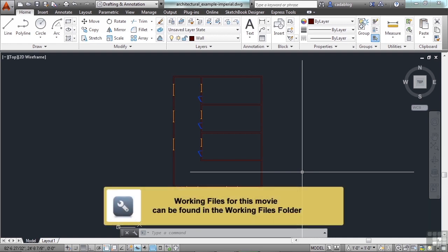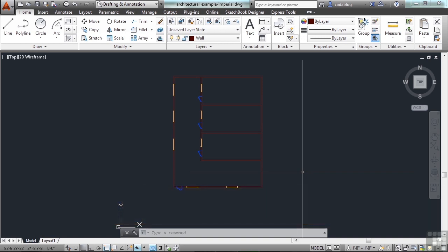Most of the time you're drawing, you won't have a layer you need or want to use. That happens. To eliminate this issue, I recommend that you start every new drawing with a template file. That'll have most of your common layers already in it that you're going to use. Just maintain that template file, keep it up to date, and when you develop or make new layers, make sure you include it in there, especially if it's one you feel that you're going to use often.